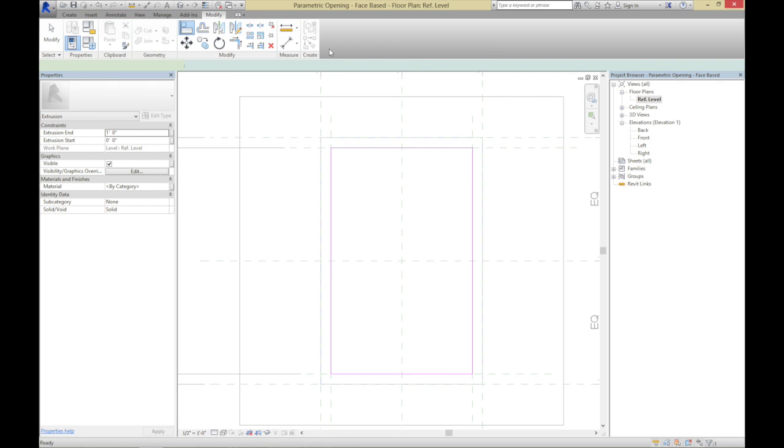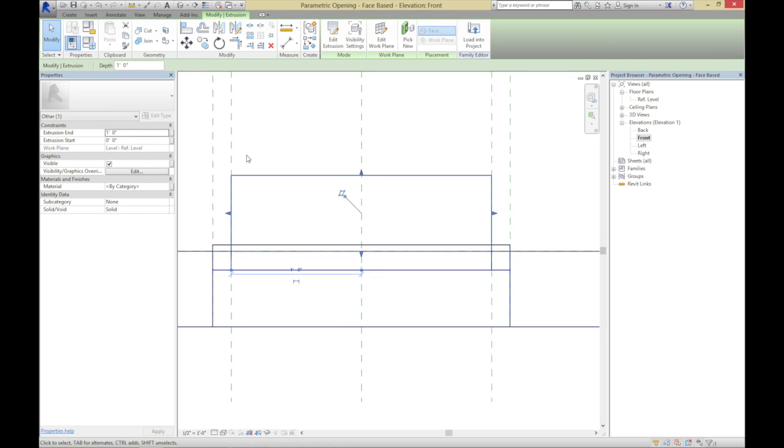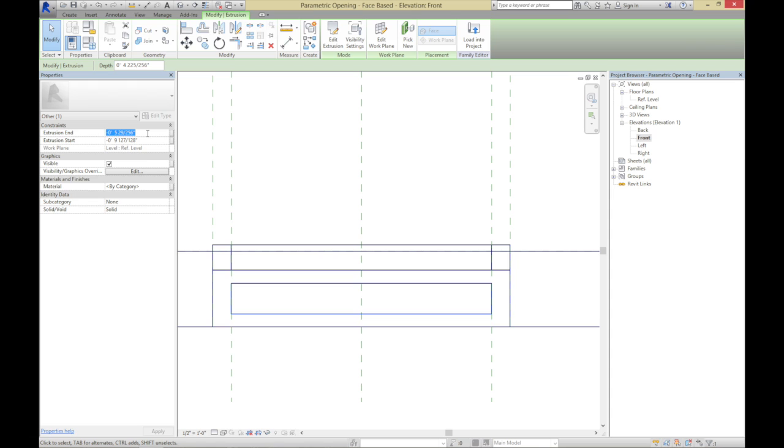Okay, super. Once again, I'm going to adjust the thickness of that. Let's come back and take a look. You'll see it's hanging around out here. There's the outer surface. Let me go ahead and do something like this. We're going to go through and maybe set the outer surface to 0. For the inner surface, maybe like -3/8 of an inch, something like that.